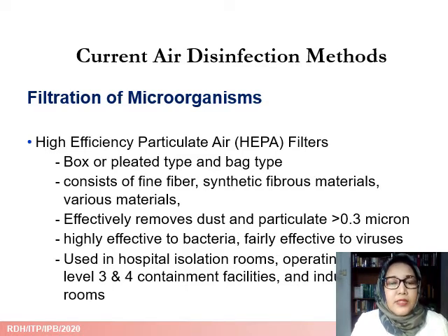These HEPA filters can be box or pleated and bag type, consisting of fine fiber, synthetic fibrous materials, and made of various materials. They can effectively remove dust and particulate above 0.3 micron. Highly effective for bacteria, although it's fairly effective only for viruses. It has been used in hospital isolation room, operating theaters, level 3 and 4 containment facilities, and industrial clean rooms.